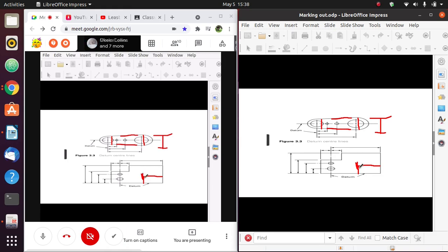Sana you'll see this when you're doing drawing, AutoCAD, or when you're using computer applications and you want to specify a specific point on your workpiece or your drawing, then you use rectangular coordinates, where we take the dimensions relative to datums and they're at right angles to each other. Now, polar coordinates are where dimensions are measured along a radial line from the datum.